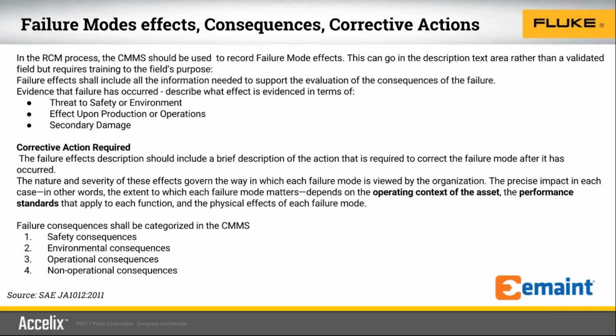So we look at failure modes, consequences, and corrective actions. Talking here about the RCM process, really what you're looking at is establishing what the consequences are. In other words, is it worth doing? We'll have to know based on what the consequences are. What are the effects? What is noticed? And this really depends on, at the moment that a work order is issued, what exactly was noticed?